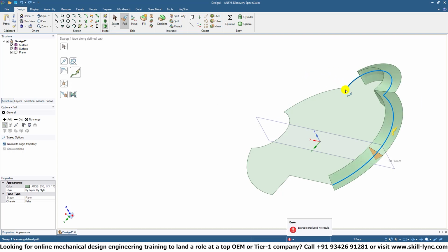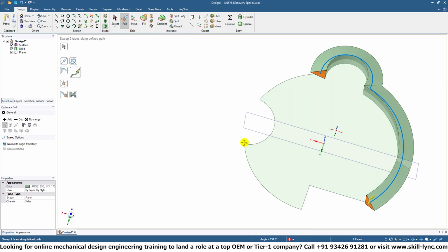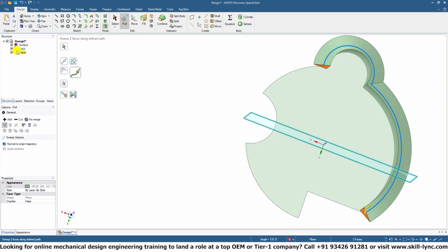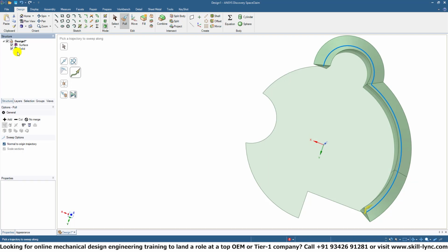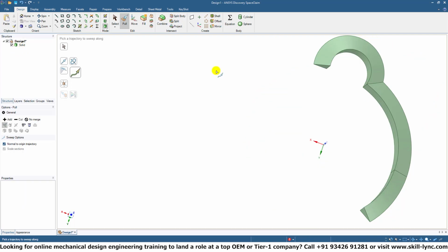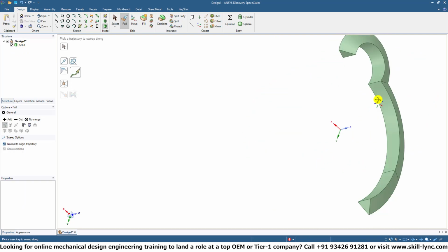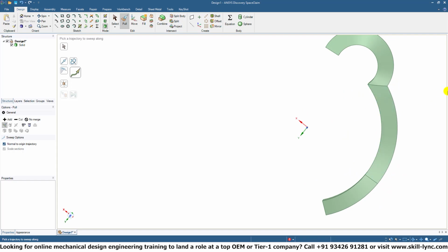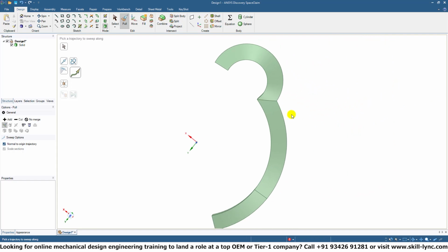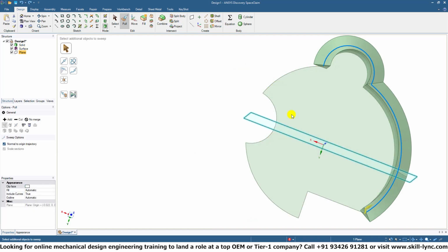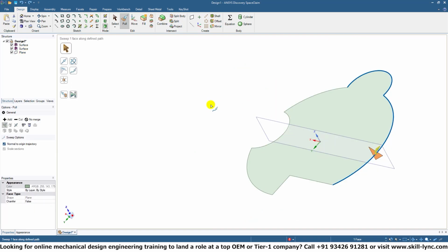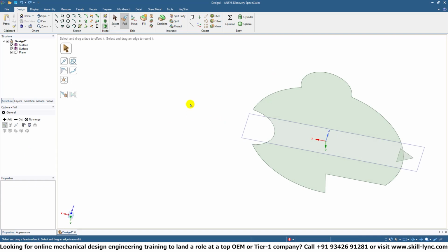Then it automatically stops me at the end of the path, right? And then again, if you wanted to clean up your sketch a bit, you could remove all of this additional helping geometry at the end once you're happy with your sketch. However, I do advise against that, because if you make a mistake or if you want to change your design later on, it's useful to have all of this additional helping geometry.